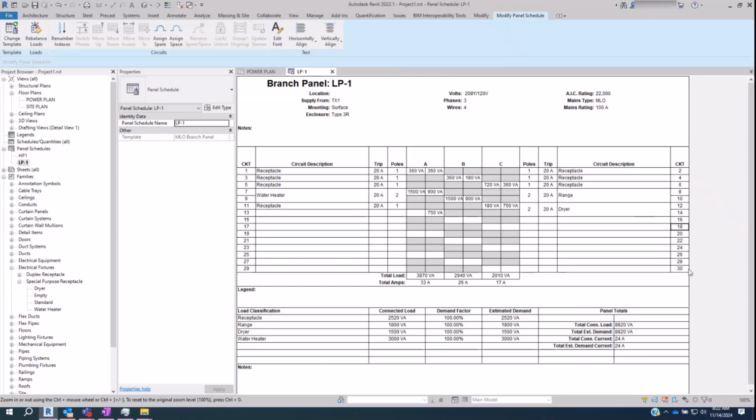There is a time when you need to do that, and it is good practice. However, 98% of the time, it is good practice to actually have spares and spaces. Address the 2% of the time first. If you know that you're right at 80 amps, because this is a 100 amp panel board, it's 80% rated.